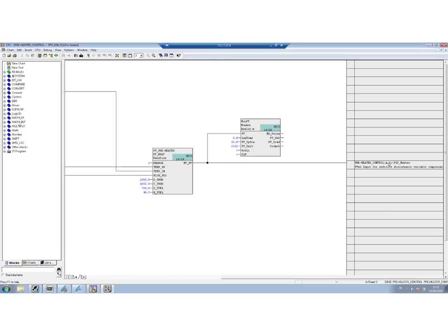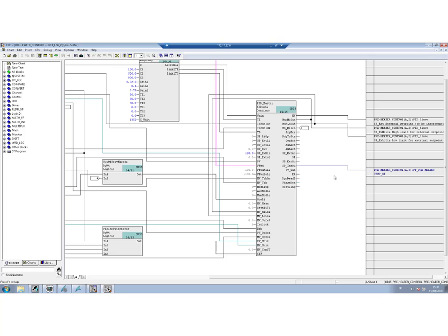This pre-computation of what you should use as a fuel flow, as you can see, is going to the master PID, to some input feed forward, and here is this PID master controller. So it is really the temperature controller, and this signal is going into an input feed forward. We had called it MV underscore feed forward, but as you can see, the name can change.